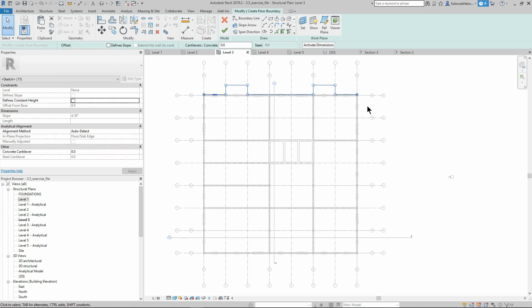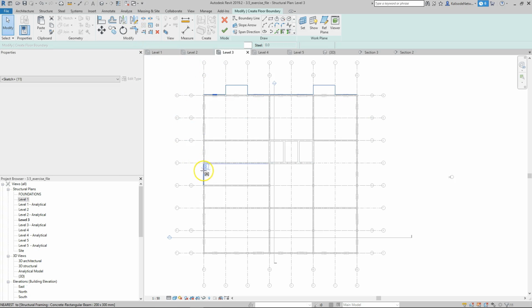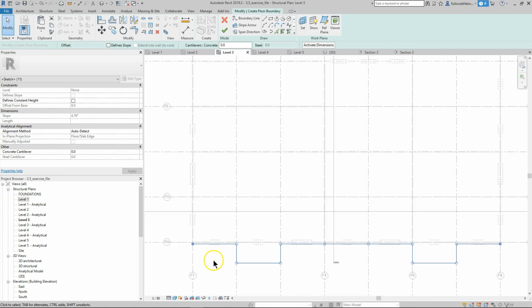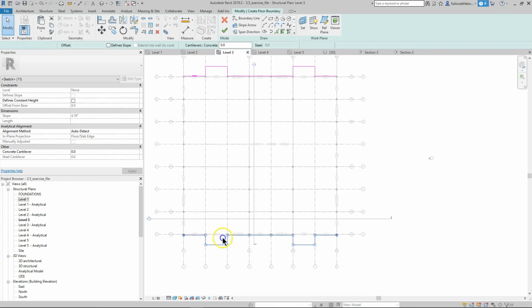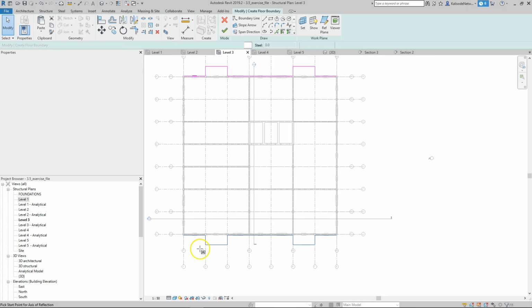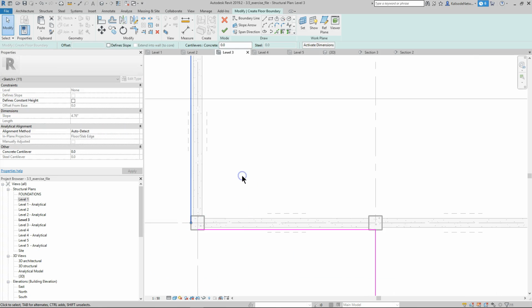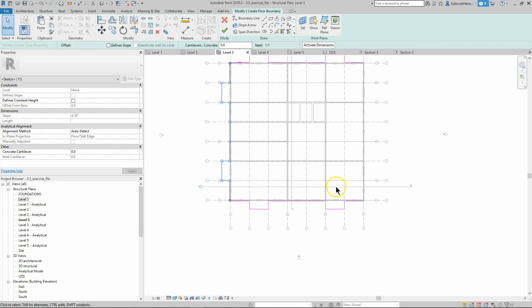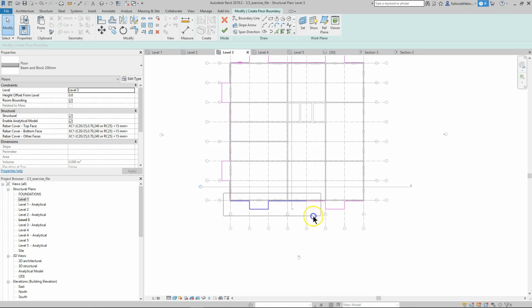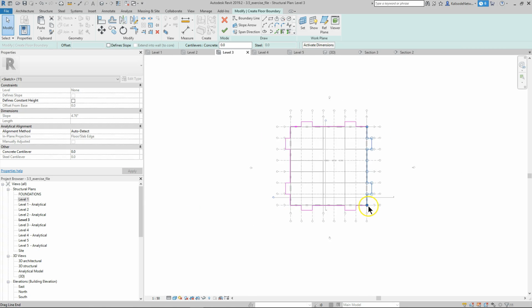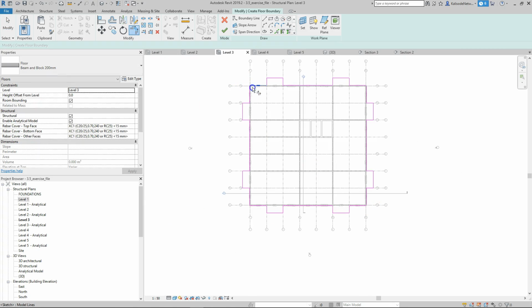So I select it, and what will I do? I will use mirror. I select a midpoint, and I'm doing the south facade of that, and I will show you how to use mirror again, shortcut DM, and I do a diagonal, which is a mirroring axis, and this will generate the vertical one, and I will select this again and mirror it again in here, and I've done this other side too, and I will trim.